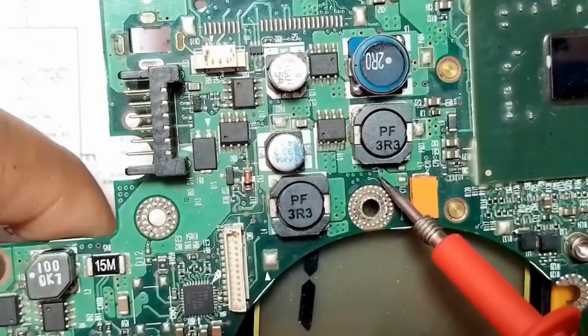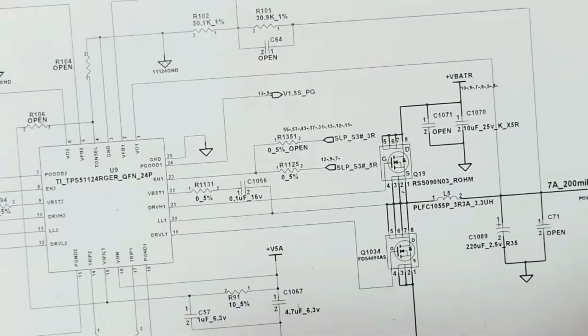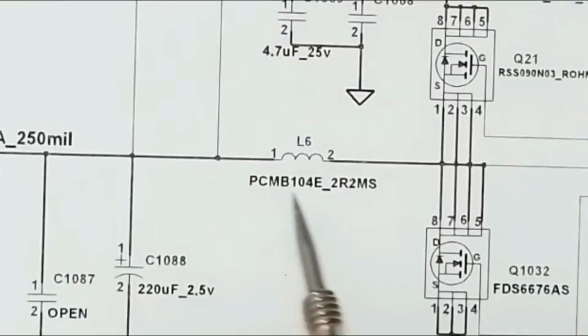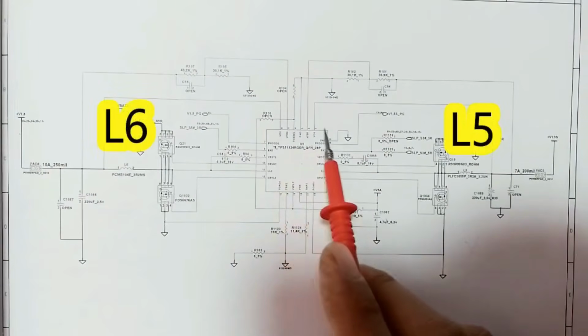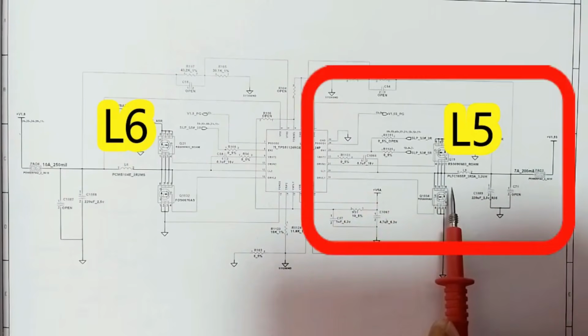I'm going to show you these inductors in the circuit diagram. So let's find L5 in the circuit diagram. Here we go. We have L5 here. And here we have L6, as I told you before. This is the circuit where we have the short circuit. So here in this channel we have the short circuit.